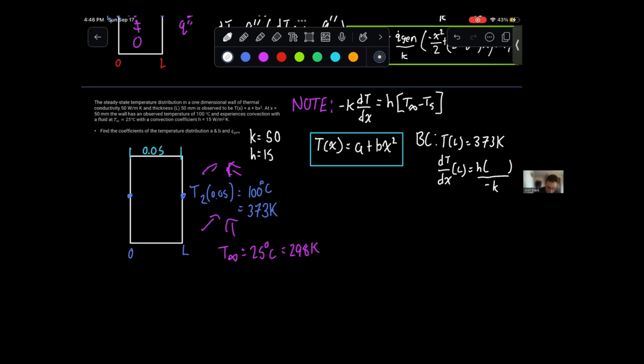And we want the flux to be a positive number. If the flux is a positive number, this means that the direction that we're defining as positive is the way the flux is going. So let's put it this way: anything going to the right is our positive. Meaning I think T1 is going to be greater than T2 because our heat is going to be transferring from left to right.